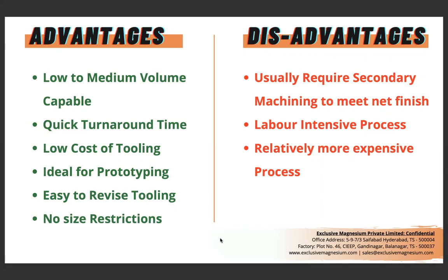Disadvantages: since you want the metal to flow easily through the sand and fill the complete cavity, the majority of the manufacturers will account for a higher wall thickness than required. To give you the near net finish later on, they will use machining to give you the finished part. So sand casting will have a higher level of machining than any of the other processes, and because it's a skilled process and uses extensive labor, it is also an expensive process.